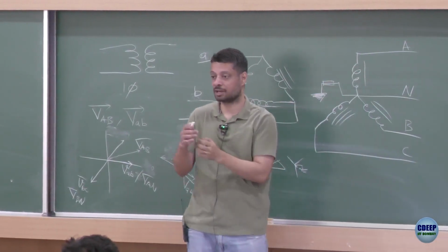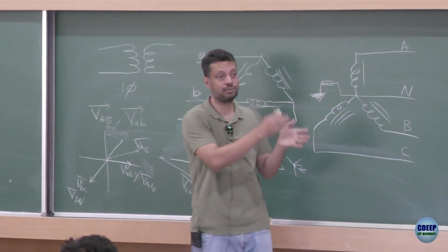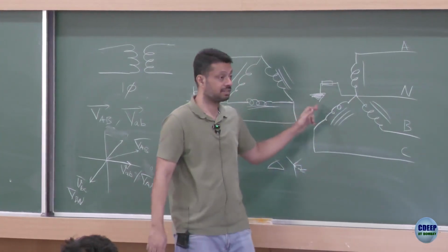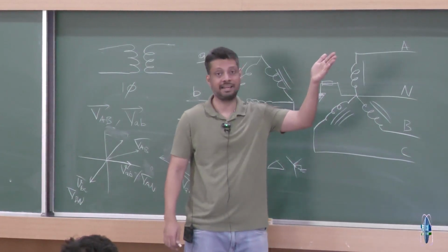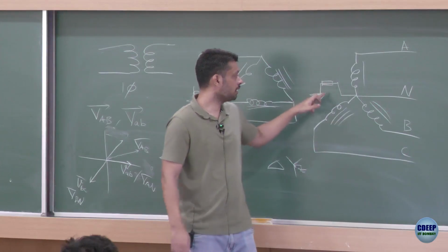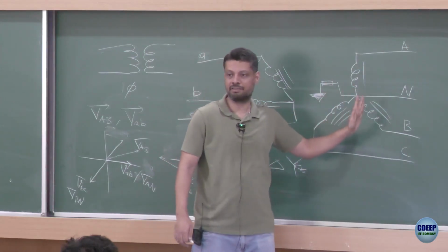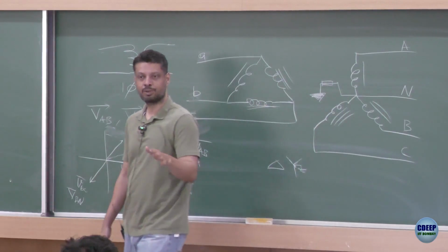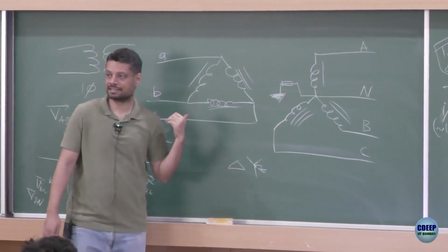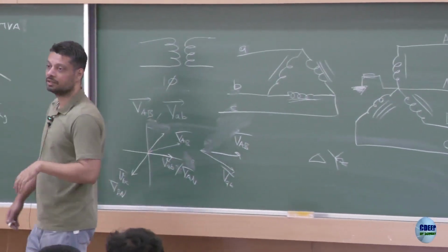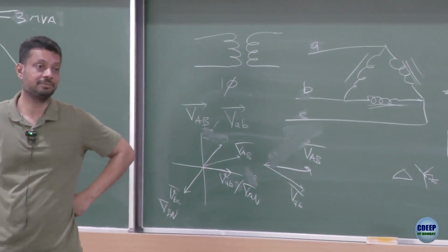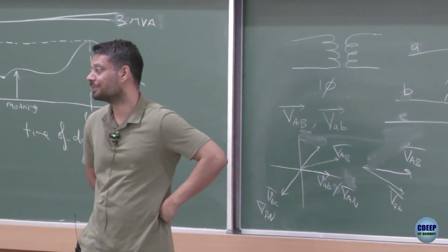So, you can design your gloves, you can design your shoes, you can design the insulators on that well defined 400 volt. If this is not earth, I am standing there, I touch a line, I don't know how much voltage will get applied across me, right. So therefore, load side it makes sense to have a star, right. Then the question is on the source side, on this side, you could have still had a star, right. Why do you want a delta? That's the next question now. Difficult question. Anyone who has answer?